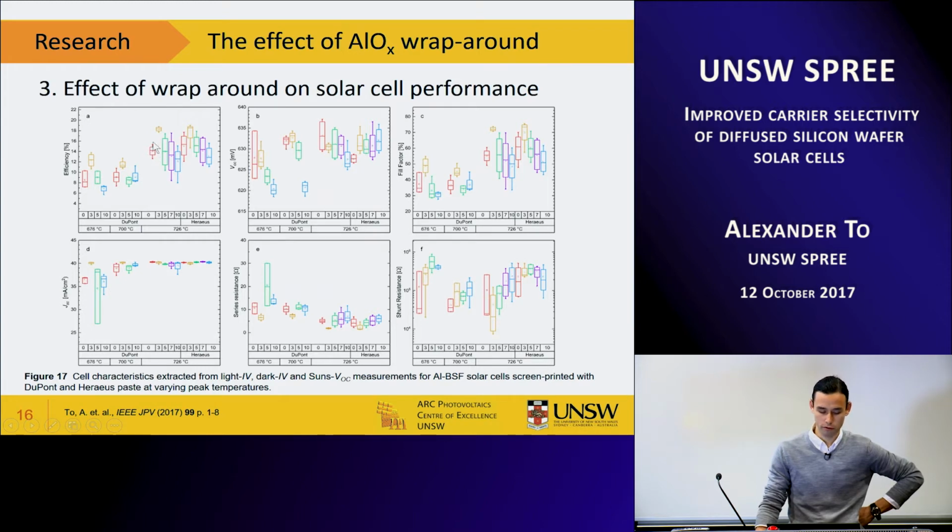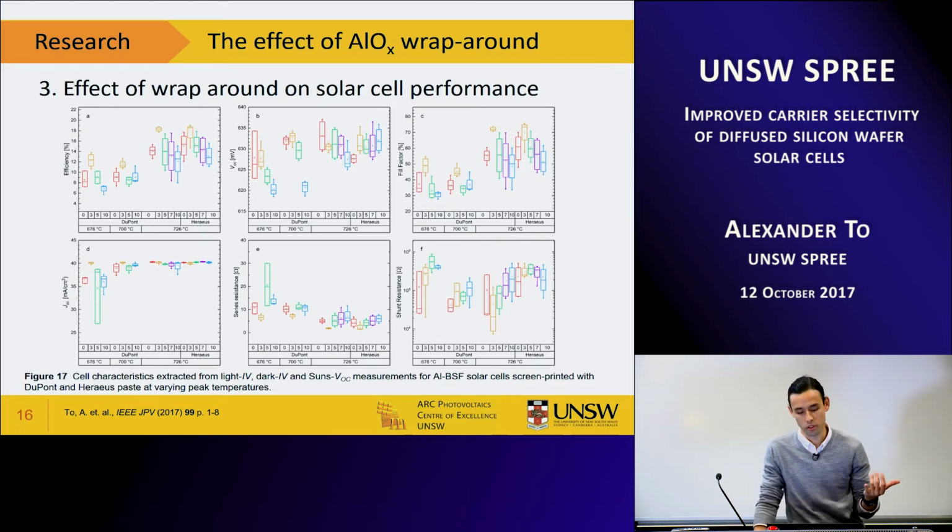Almost a 4% relative increase. So that's really showing the effect that this can have in the case that your series resistance limited, but also hints that perhaps you can drop the surface concentration a bit with these cells and try and get decent performance. Unfortunately, the 5 nanometer cells didn't perform as well as the uncapped case or even as well as the 3 nanometer case. And there's a lot of spread in this data, so I think that's probably related to some non-uniformities in the deposition or something.